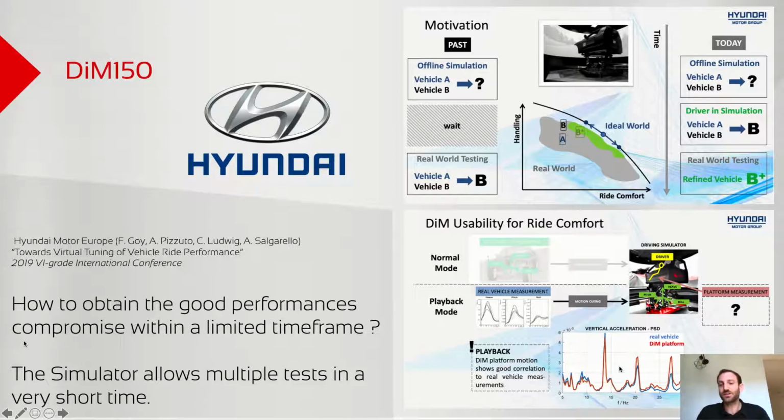This is what you can see on the right, that between 5 and 30 Hz, the rear vehicle and the D platform match almost perfectly. So the conclusion was that the driving simulator is a valuable tool for ride estimation.